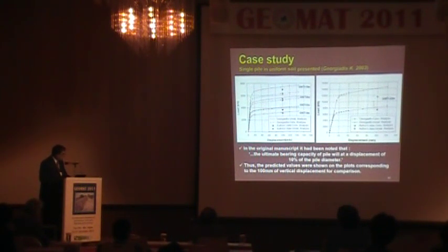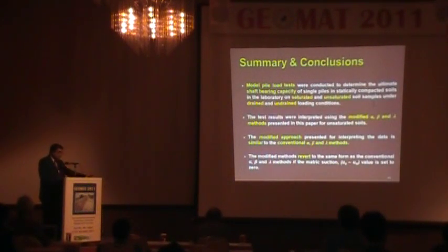You can see that end bearing resistance in a very long pile is not that much in a till soil. The shaft resistance is the chief contributing parameter all along the length, and you can see that the results are reasonably good, but we are doing more studies to understand the end bearing capacity, and that would help to get better results. This point is the one which we have estimated, and this is from the finite element, and you can see that there is a good comparison.